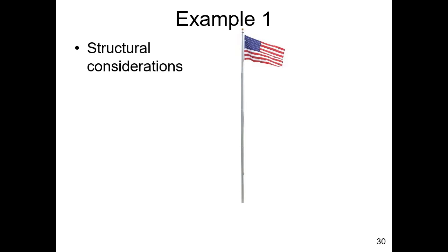Well, that's kind of the opposite of the way you would look at it. First, you would look at a design condition. So let's say you're a structural engineer. The structural engineers have entire code books on what design conditions you should use, no matter where you are. So for example, let's say you're designing the roof trusses for a building around here. The design depth of snow is 4 feet.